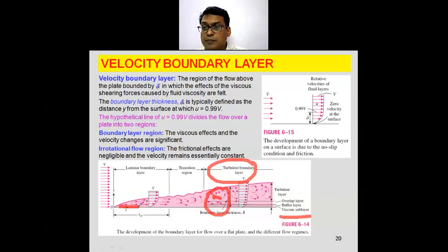Now when you see this viscous sublayer, the velocity gradients are very high. If you magnify this part here, you can see this sublayer, the velocity gradients, velocity values. These arrows indicate the numerical values for the velocity. A small arrow means its velocity is small, a big arrow means its velocity is large. That is what the velocity vectors represent with the numerical values. When you calculate it with the help of computational fluid dynamics, for example Fluent software or any other CFD software, you can see the different velocity vectors and they have a specific magnitude, a specific value for that velocity vector.